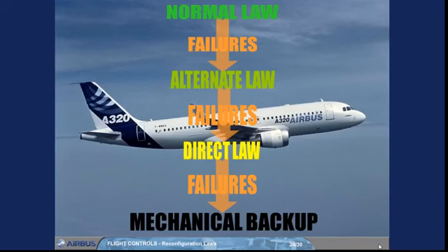The mechanical backup is a temporary mode, because in most cases, e.g., by resetting the flight control computer, you will be able to recover from mechanical backup to either alternate or direct law, depending on the type of failure. We will now see a brief summary of the different laws and their associated protections.